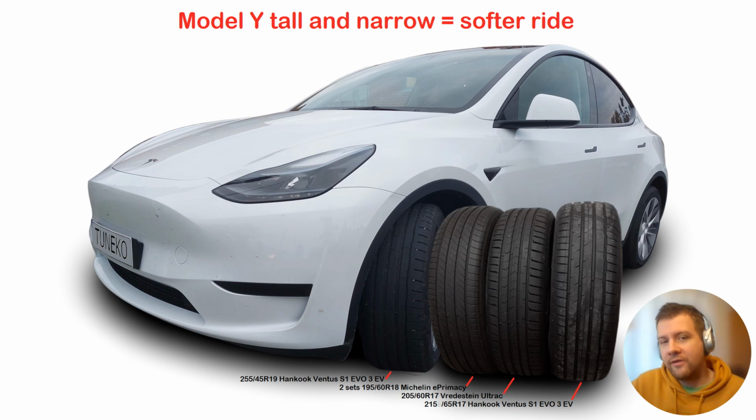Softer ride, and you can get it in many ways. One way is to install softer springs, softer dampeners, or narrower tires. And here I will go through the physics of how you get a softer ride with narrower and taller tires. It also has energy consumption benefits, which I have already talked about in a previous video, but this is more about ride hardness and the impact of moving to narrower tires.